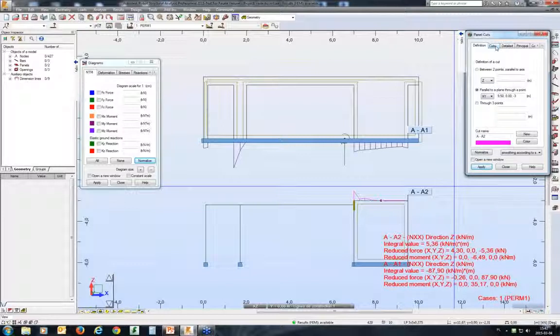Okay. It's again always, let's name it reverse engineering. When you create a model, you should ask yourself what kind of results you want to obtain for that. So if you want to see the results as a map for the whole shear wall, create them based on panels next to each other.